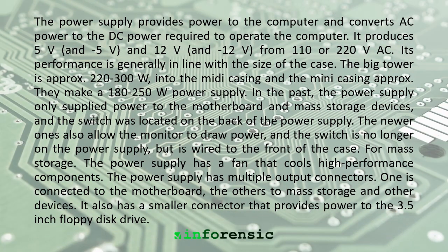The power supply provides power to the computer and converts AC power to the DC power required to operate the computer. It produces 5 volts and -5 volts and 12 volts and -12 volts from 110 or 220 volts AC. Its performance is generally in line with the size of the case. The big tower is approximately 220 to 300 watts, the MIDI casing the same, and for the mini casing they make a 180 to 250 watts power supply.